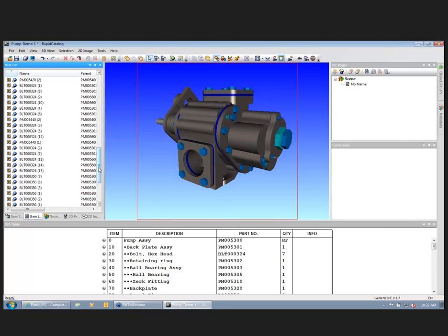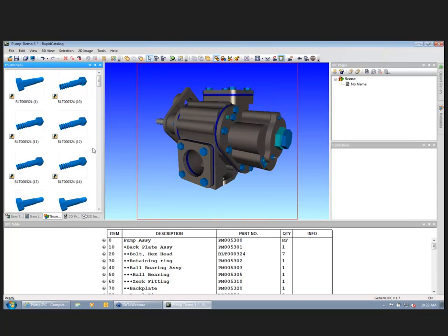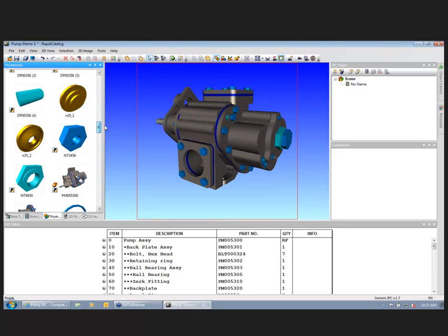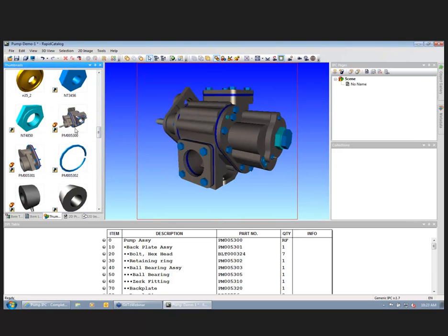We're also able to view these components in a list if we want it broken out from that assembly structure. And then if I want a graphic representation, maybe I don't know the part number, but I know what the part looks like, I'm able to come over here to the thumbnail tab and scroll down, and I can start seeing a little thumbnail of any component I want, and I can pick it that way. Down here at the lower portion of the tool is my parts list table. DPL stands for Detailed Parts List. Basically, this was the bill of materials that got pulled in, which we can edit manually if we want. It's completely interactive. Maybe if I wanted to spell out assembly, I could add that.